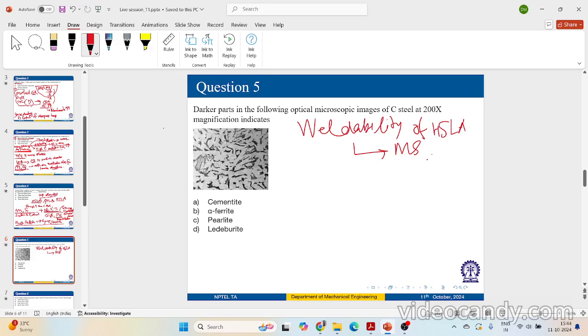During welding, if you are using any kind of filler metal, that is often selected on the basis of matching the strength of your base metal. Because you want strength in your structure, we don't compromise on your base metal strength. So what people do, if they are using any filler metal, they choose a filler metal similar to what they are using as base metal.